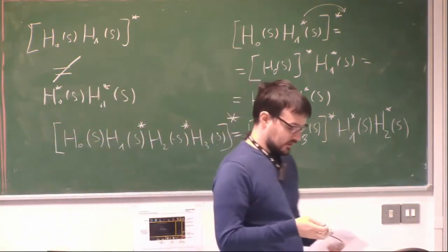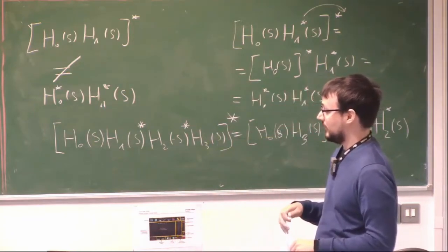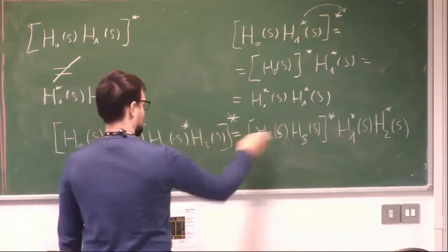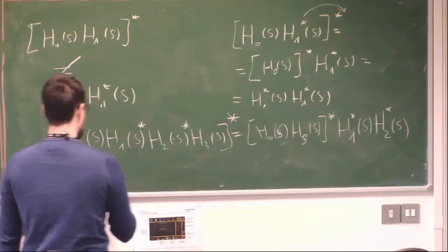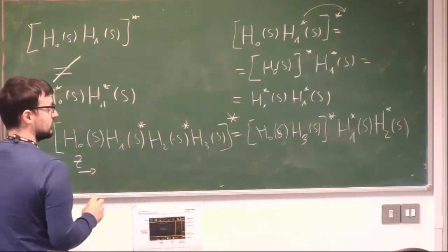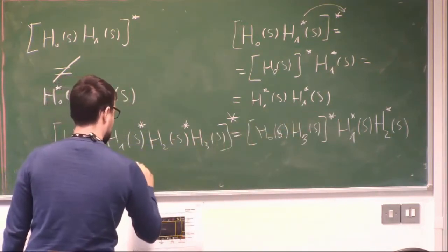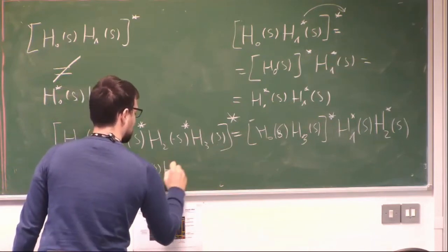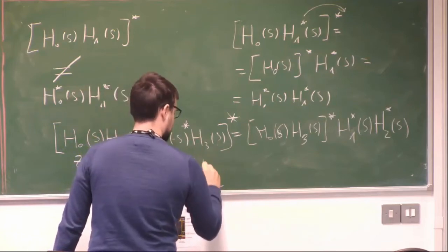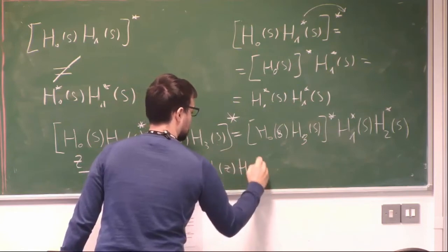And it's actually very useful in exercises to go from the S domain to the Z domain, because now if we look at this and we want to write the Z expression for this, the Z transform of that is the Z transform of H0(s) multiplied by H3(s), times the Z transform of H1 times the Z transform of H2.